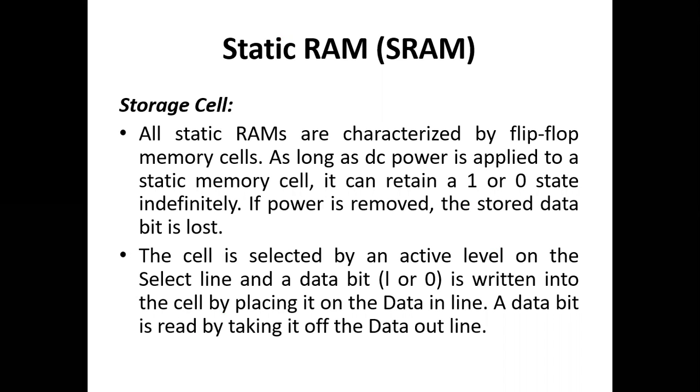Static RAM: all static RAMs are characterized by flip-flop memory cells. As long as DC power is applied to a static memory cell, it can retain a 1 or 0 state indefinitely. If power is removed, the stored data bit is lost.